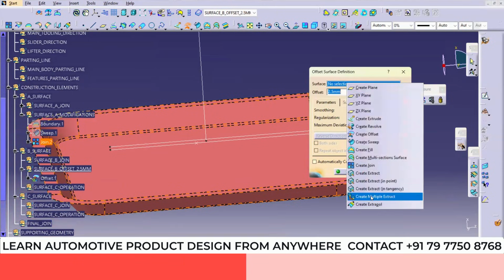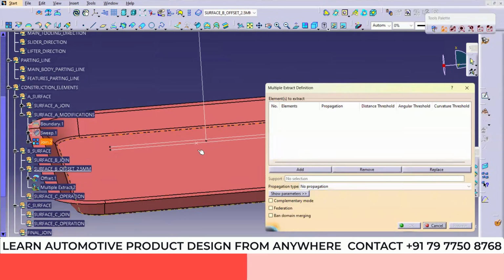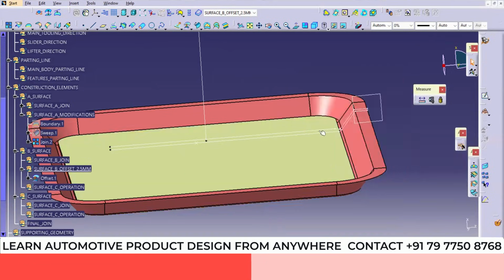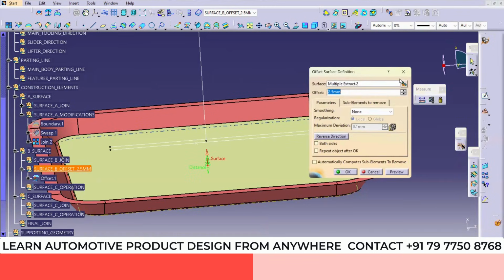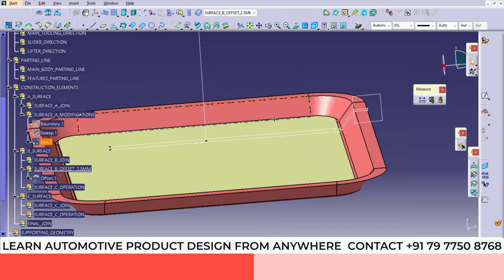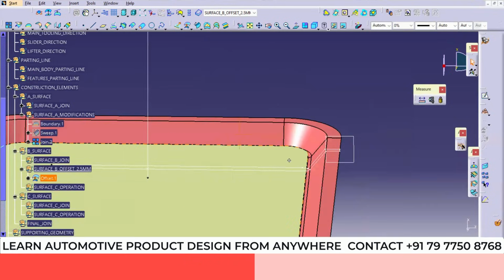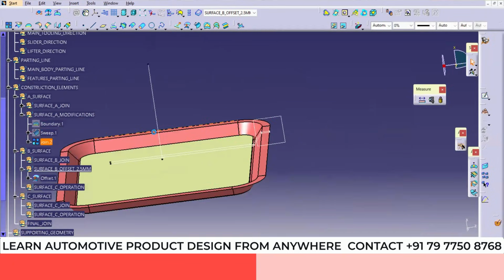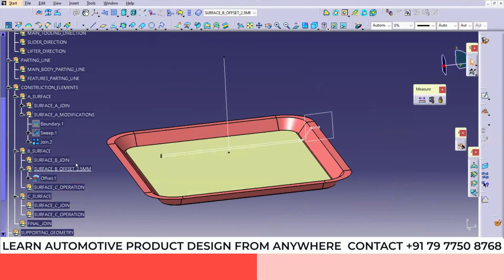Right click. Here you can use the extraction because we want this patch, right? So select this, click OK. Because the offset is editable here, multi-extract is a sub command. If you want to change the offset value, just double click and change the value. Then here this patch is 1.5, right? So we can use 1.5 here.